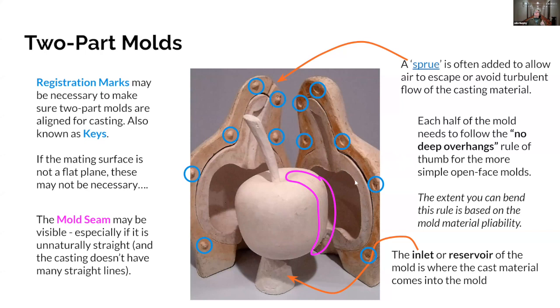This is a mold that has a thin rubber layer around the part to get the detail, but if you were to peel that out, it'll be floppy. It won't hold its shape, especially when it's full. If it's full of plaster that's heavy, you need a rigid shell that the rubber part of the mold snaps into to hold the shape, and then it's like a clamshell, it just goes together.